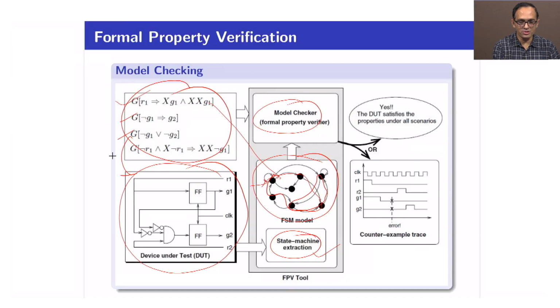So, there are two parts here. The most important is the FSM state extraction and the algorithm. In this course we will mostly focus on this algorithm: how do you implement this LTL or CTL model checking algorithm, when you give such a property, and how do you check it in a given FSM. This is the first part we will do, and I will talk about more at the end of this class. You will understand more on this.